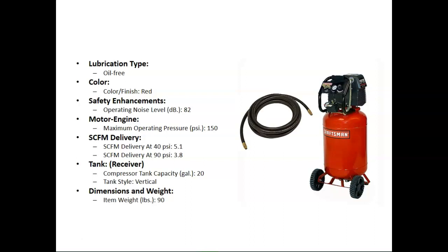I figured. 70. Noise above 70 dB over a prolonged period of time, they start to damage your hearing. Which is why most noise levels, if it's over 70, you're supposed to be wearing what? Hearing protection of some sort, yeah?